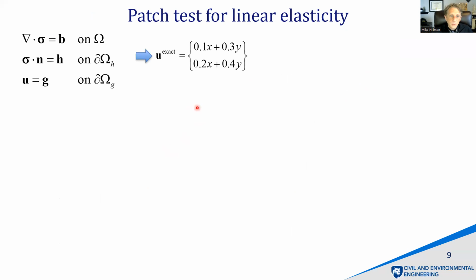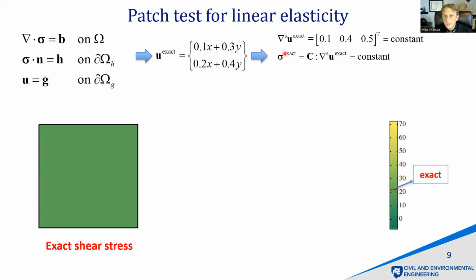Okay, so let's look at this idea of trying to pass the patch test. I'll take just a very simple problem. I'll start with elasticity, then I'll go to thermoelasticity. Start with elasticity. I'll design this with a linear solution. Okay, if I have a linear solution, then my strain is constant and my stress is constant. Okay, so this is just a manufactured problem with a linear solution.